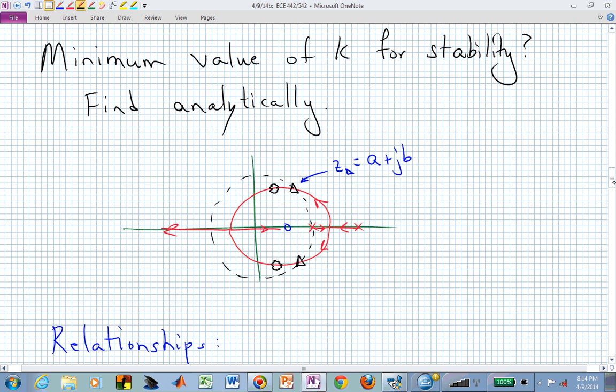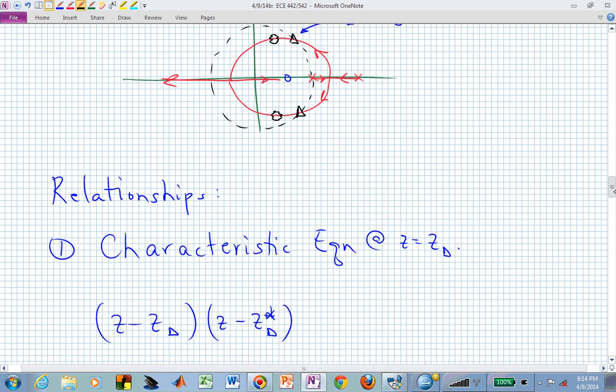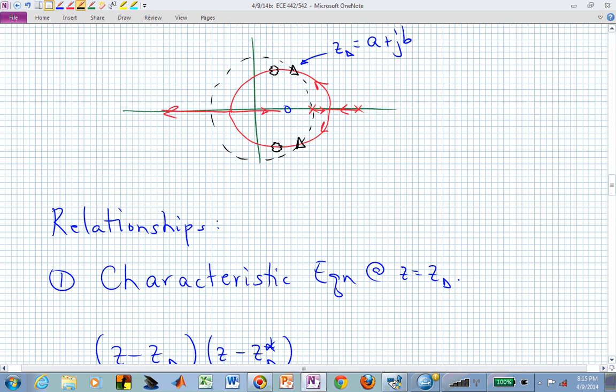So you're looking at a gain of k a little bit bigger than 2, and it's not going to probably be all the way over to be 2 negative real roots, which is at the 3.7 value of gain.